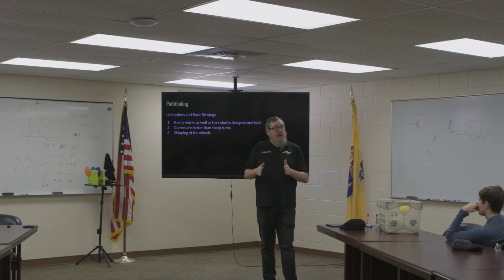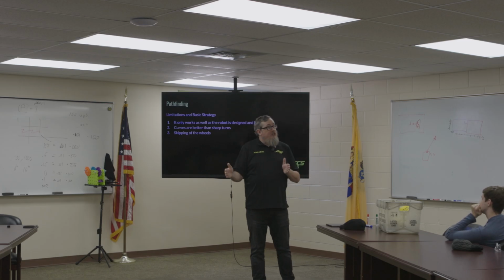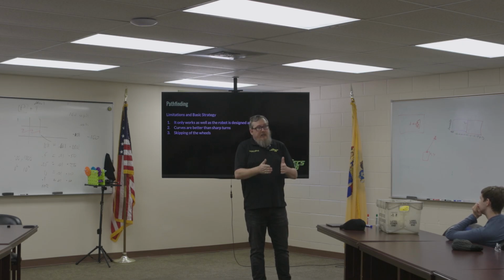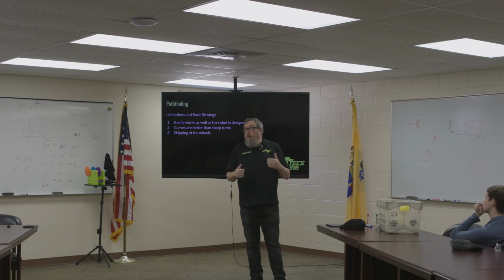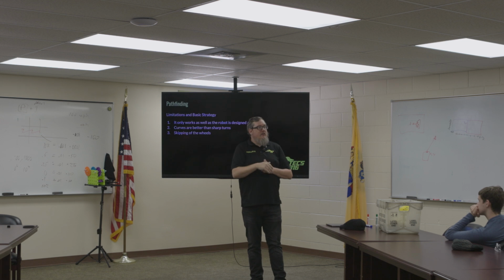It allows us to correct like 1 inch to maybe 3 inches, which is perfect, which is what we needed, right? Odometry gets you within 3 to 6 inches, right? So if we can correct that 3 to 6 inches, which pose estimation will do, we're great. But if it's more than that, we start running into problems. It will start correcting, but it won't correct enough by the time it gets to the target.